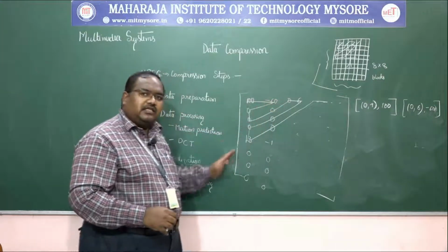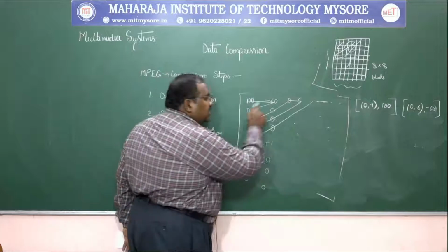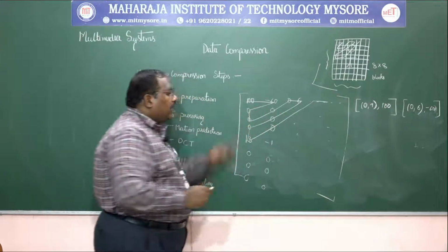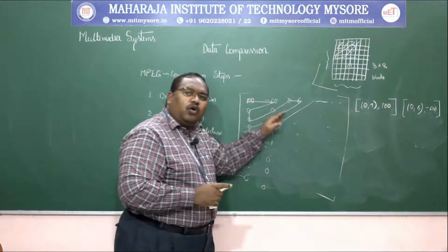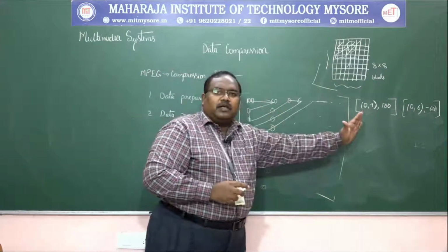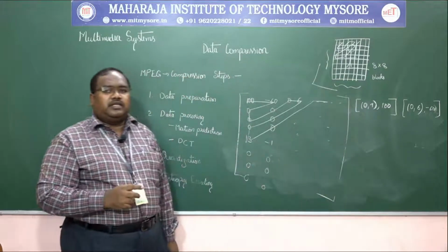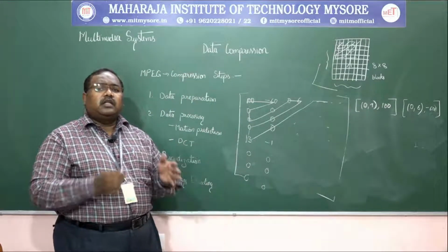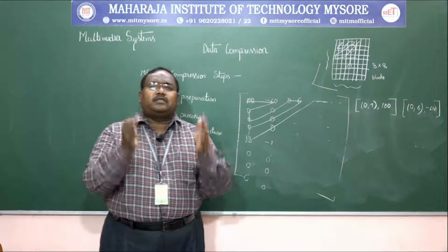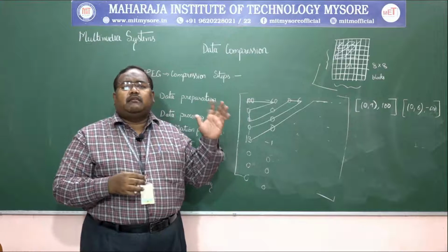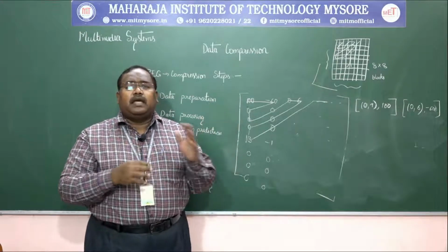This goes on like this. So that's why we use the zigzag pattern. With the way we moved, we completely traverse the whole path and write the representation in a single-dimensional equation. So then we get a totally compressed image. This is how the MPEG compression happens.